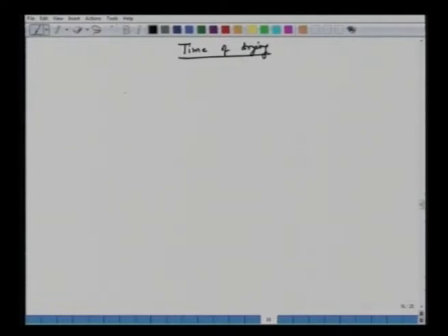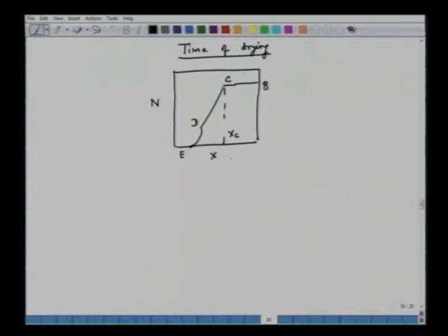Okay. So again, we have to start from here. We have N versus X. If we leave aside the initial adjustment, then you have B, then you have C, where the rate decreases linearly, then non-linearly. So C, D, E. You can mark this XC, critical moisture. Corresponding to this, we have NC, critical rate of drying. But notice that this is flat, so the critical rate of drying is constant between B and C. Then it decreases, so this is a falling region.